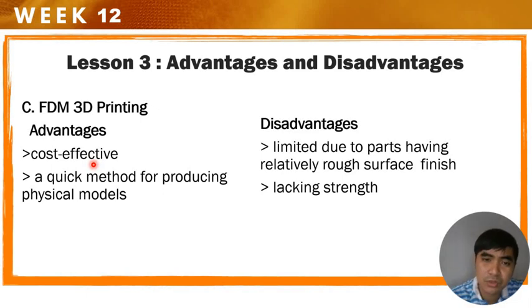Disadvantage: limited due to the parts having a relatively rough surface finish, and lacking strength because the parts here are made in a fast manner, meaning they are not that hard compared to SLS and SLA, and their surface finish is not smooth, they are rough.